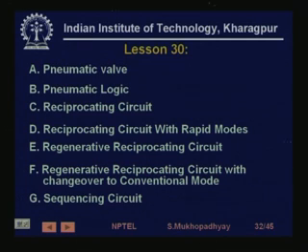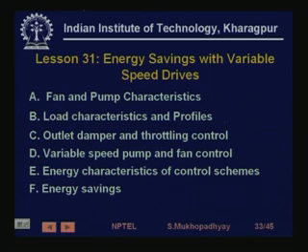After that, we took a look at electric actuators, but before taking a look at electric actuators, we first understood why there is a definite trend among industrial control or drives that people are going for variable speed drives. Now, what is the basic advantage of variable speed drives, and showing that variable speed drives can be huge, very significant energy savers.